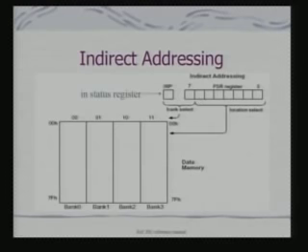Once you access the INDF register, PIC uses the address in the FSR register to access the operand in the memory. So you can see that indirect addressing in the PIC requires not just one instruction but 2 instructions for specifying the address.